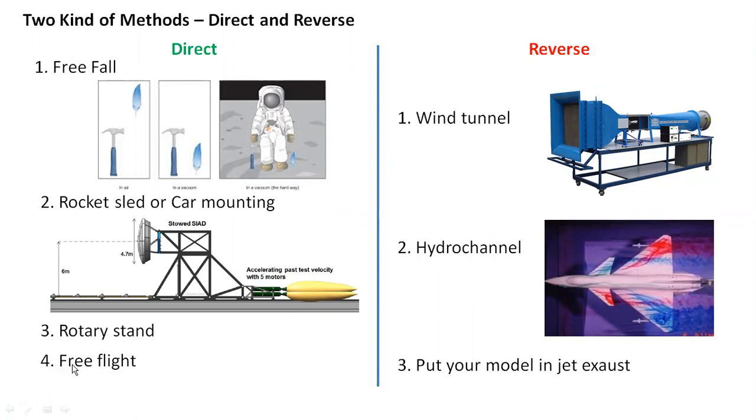And four is free flight, a very reliable and very costly method. You can do free flight with a full-scale aircraft, and you must do free flight testing at the last stage of your aircraft development. Also, for reduced cost, we can do free flight with scale models. Sometimes this is done for very dangerous situations like for stall condition or spin condition, spin recovery, and so on.